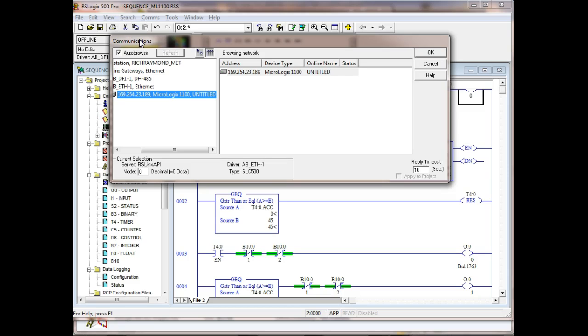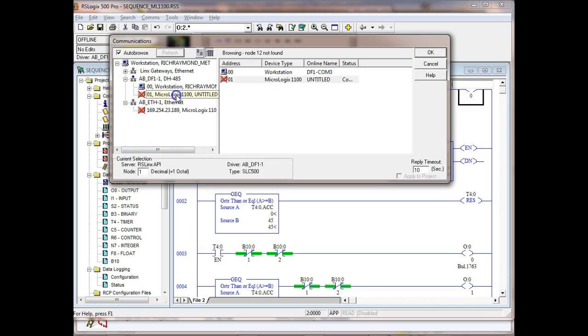And if it comes up and says, hey, I'm online, then we're okay. It says this guy's not online because I was using the Ethernet input last time I talked with him. So right now we're up here on DF1, so I'll go up here and see if anybody's active on the DF1 input, which would be this guy, and see he hasn't found anybody yet.